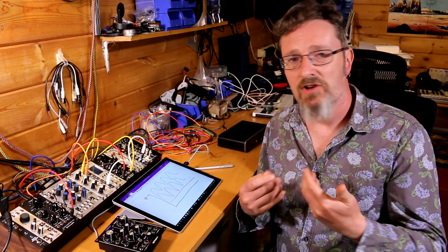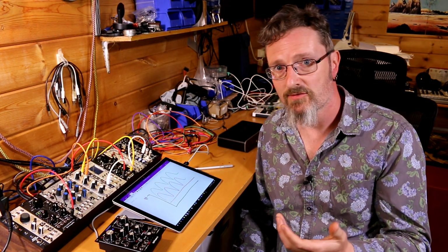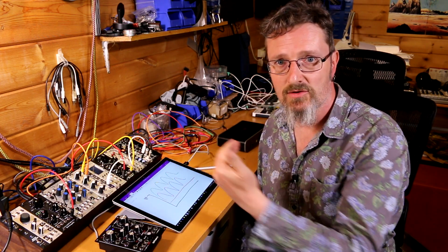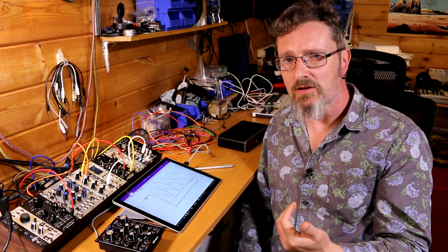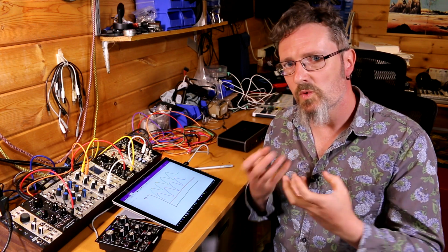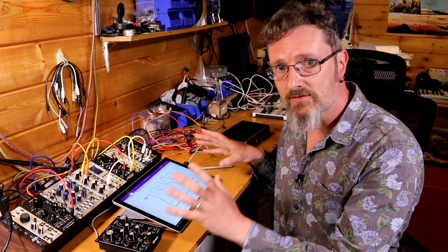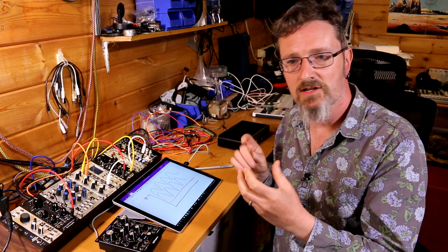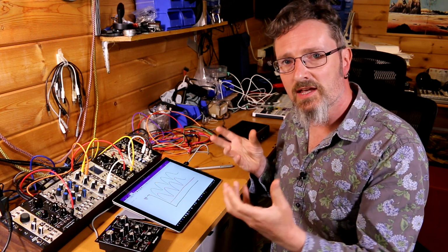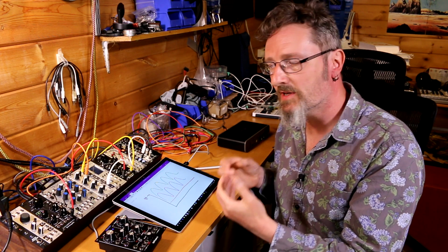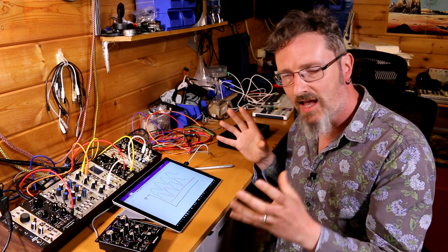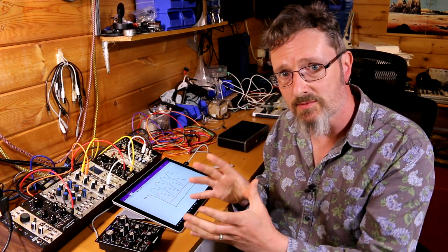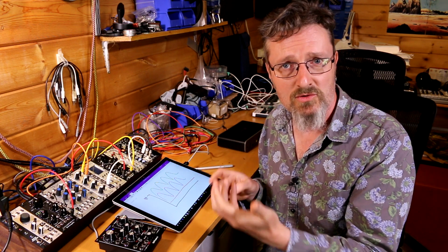Or not. I mean, it really depends. You can do a lot of the similar stuff with a MIDI to CV converter. You can indeed take notes out, stick them through that, and then CV through the rest of your rack. But I think what's interesting about CV is that it just works differently. If you're committed to using CV within your Eurorack and understanding control voltages and how they interact and move with each other, then I think it's better to have that going directly into your computer, because you get the same level of control. You're not going through some kind of digital conversion to approximate the same settings and the same sort of control.